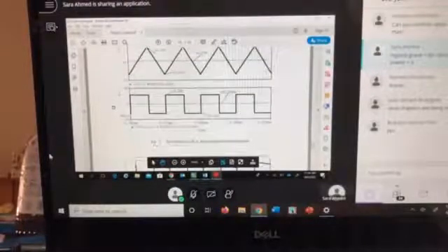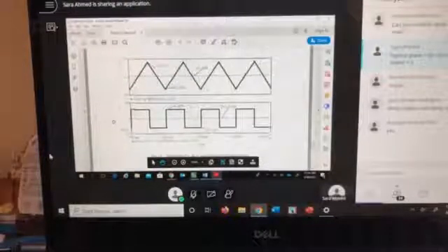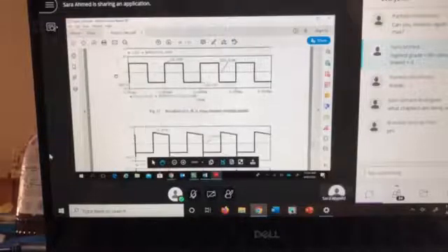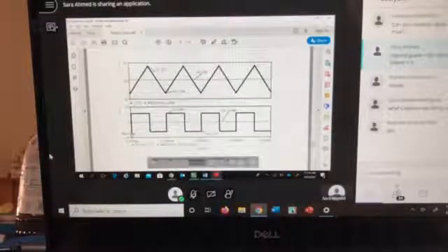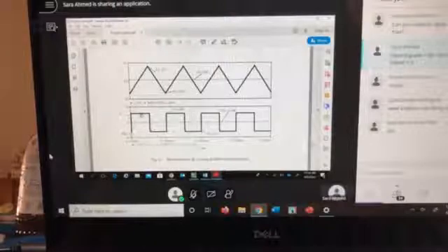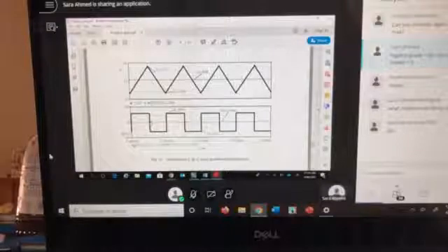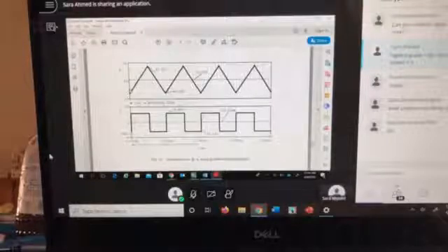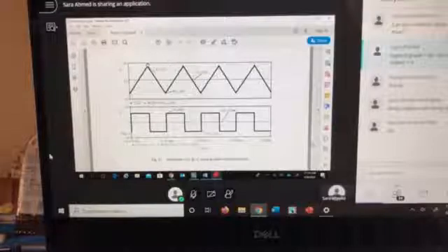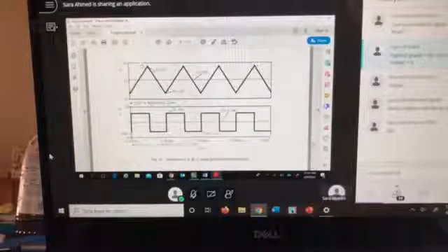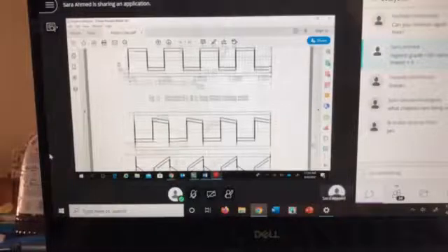IL, V of L together. And then what is IL and V of L? V of L, we know that it's a square wave. So those are the same plots that we used to plot by hand in class. Your V of L changes between the value that you calculate for the first interval, the second interval, and then it repeats. Then what is I of L? I of L is a constant value with the slope that's equal to this V of L. So when it's positive, we have a positive slope on I of L. When it's negative, we have a negative slope on I of L. And that basically is for IL, V of L.